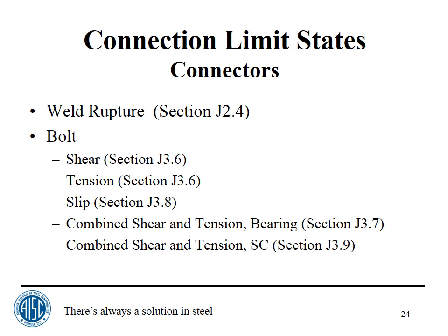Some of them were still using the yield limit state, which we really don't have to do anymore, because people are just so used to checking yield and rupture that they just check both. And I'm in that category. Some of the ones that I did for that manual, I just checked yield and rupture, or I checked the one that had the less capacity and said, well, that's good enough. But I think it's logical, to repeat myself, that since you have a rupture limit state on the weld, a rupture limit state on the base metal right next to it makes more sense than to have a different kind of limit state on the base metal.